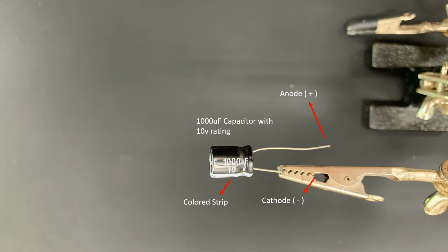If voltage is applied in reverse to an electrolytic capacitor, it fails spectacularly by making a pop sound, and thereafter it will behave like a short circuit. These capacitors are also notorious for leakage, which allows a small amount of current, in the order of nanoamperes, to run through the dielectric from one terminal to the other. This makes electrolytic capacitors less than ideal for energy storage, which is unfortunate given their high capacity and voltage rating.